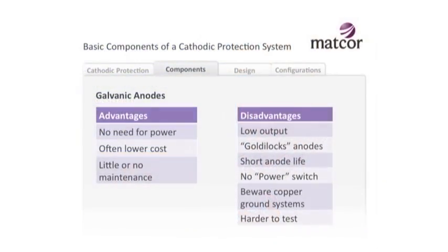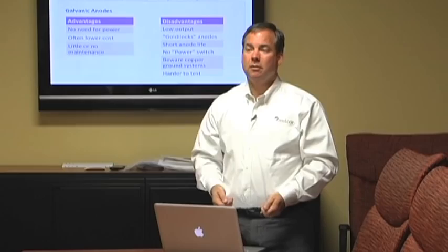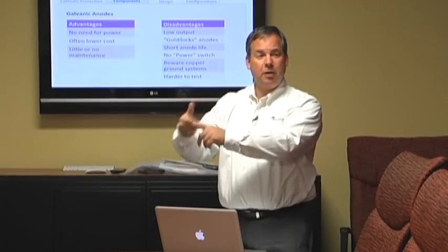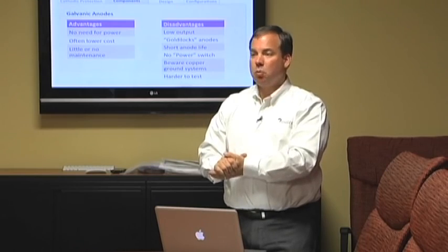There's a misconception, I think, with a lot of people in various industries that the galvanic systems are, because I have no power supply, there's no maintenance. But I make the argument that it's also harder to test, and you really never have that confidence level. If I have a power supply, I can have somebody go by the power supply once a month, look at the panel and say, yep, it's still kicking out current, still kicking out volts and amps, nothing's changed, it's still working.